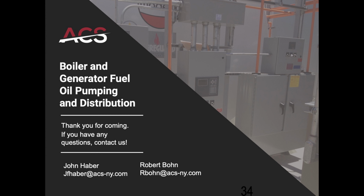Generator projects that have a header, the header is typically near the generator. It could be a couple of feet below it, but I wouldn't really go much farther than that because there are limitations on the vacuum capabilities of the engine manufacturer's supplied pump. Right, so you'd really have to look at the generator side pump specs as far as what it can pull and how far, the same situation that we'd run through with a duplex pump set in the system. You need to look at the distances, the head, the suction that it can pull.